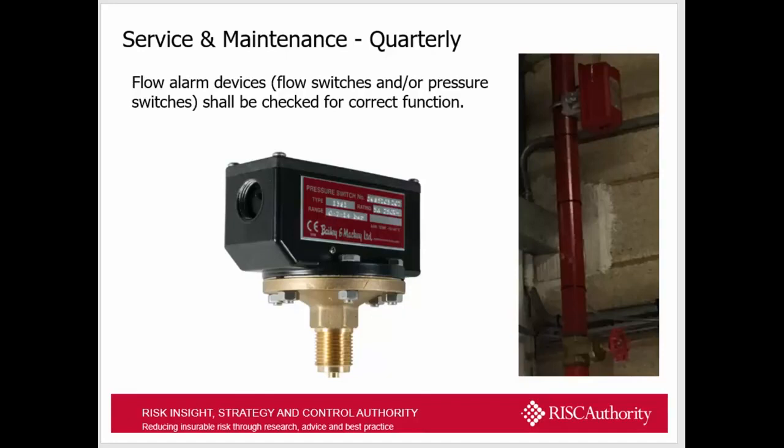So looking at quarterly, all flow alarm devices shall be checked for the correct function. So every 13 weeks, the flow switches and the pressure switches shall be tested.